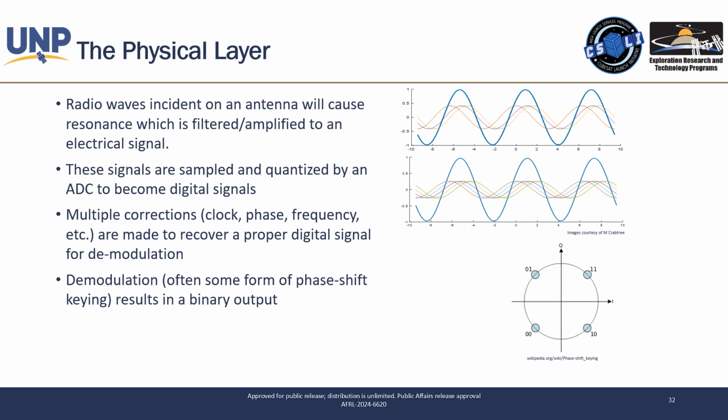And then demodulation occurs. So what we do, basically, take this wave, right? We all know from Euler's formula that we can represent a wave as a complex number, right? Specifically e to the j, or e to the j frequency, whatever, theta, right? If we assume a constant frequency, then we just care about that phase component, right?